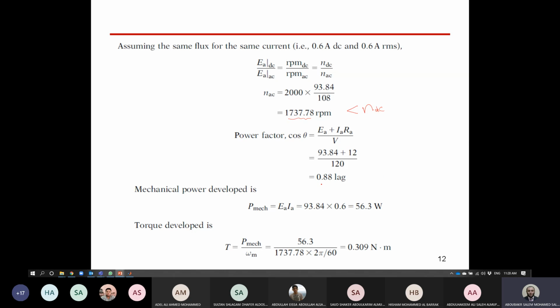Now we got the motor power factor and the motor speed. We also need to calculate the motor torque. We don't have an equation here for torque, but for the universal motor we write the average torque equals K series multiplied by I RMS squared. Here omega is the motor speed in radian per second. The EMF is K series I omega. So torque equals K series IA squared.